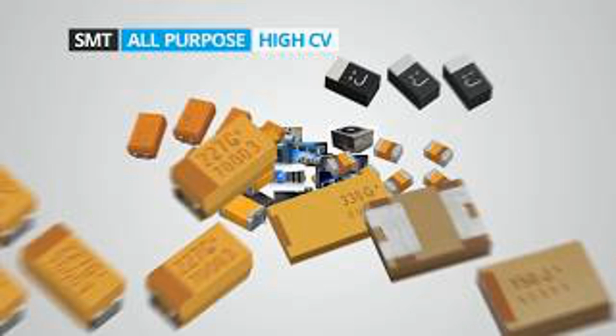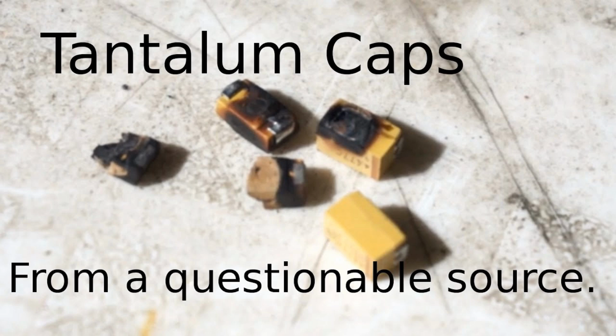6. Equivalent series resistance, ESR. Tantalum capacitors have a low equivalent series resistance, ESR, meaning they can quickly charge and discharge with minimal energy loss. This makes them efficient in filtering, decoupling, and power supply circuits where stable voltage levels are needed.